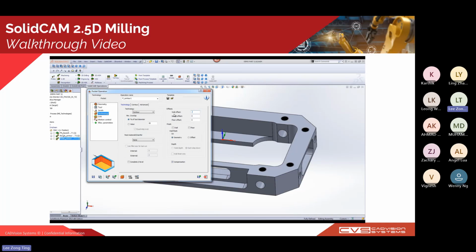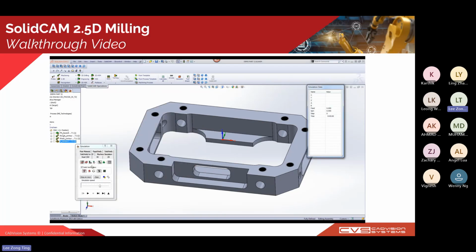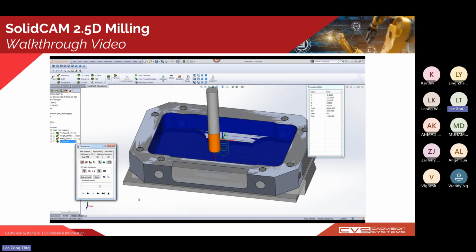And in the technology tab, it will guide you on those parameters you want to input. And on the left bottom corner of the wizard, you can see that there's a handy icon to tell you what parameters you are actually working on. And we will go ahead and set up our pocketing operation, like telling it what is the ramping strategy and what is the linking strategy, and go ahead and simulate it to check for any potential collisions and unwanted tool movements. So you can see that this pocketing operation is a success.